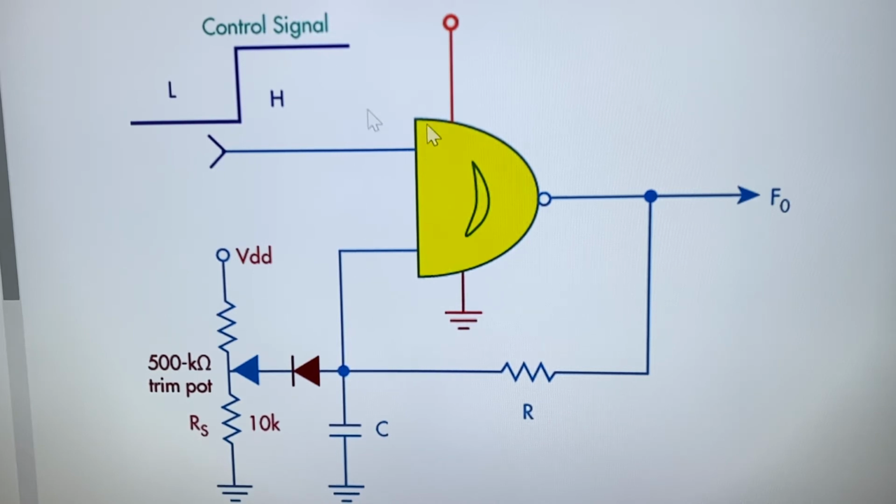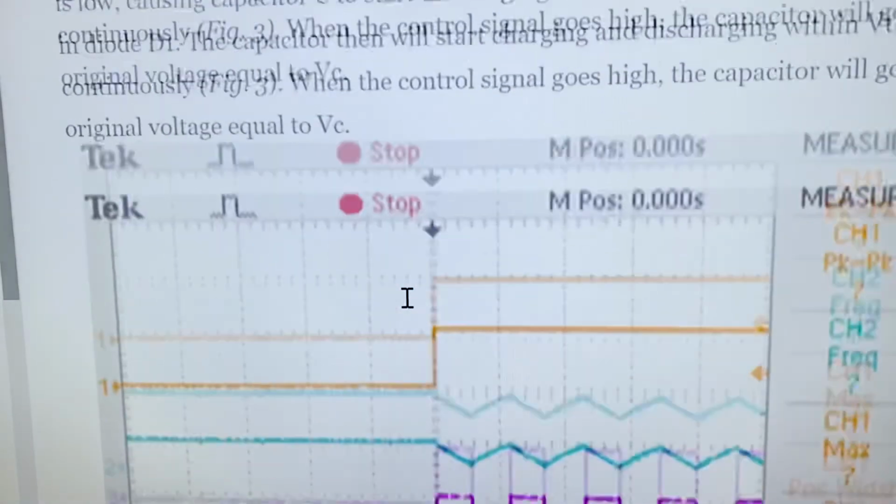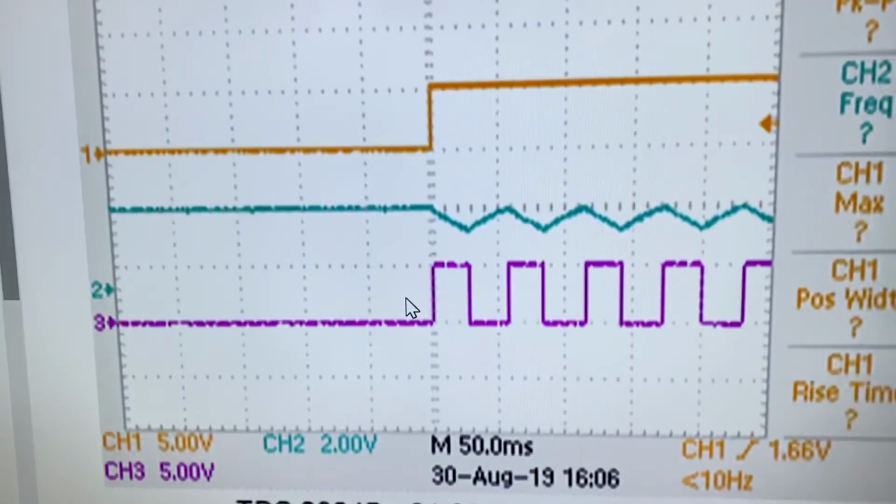So when this is 1, the capacitor from VT positive will be discharging immediately to VT negative, instead of discharging from VDD. Okay, so this can be seen here in the graph. So when this is 1, the capacitor reaches a few millivolts less than VT positive, avoiding triggering the gate, of course.